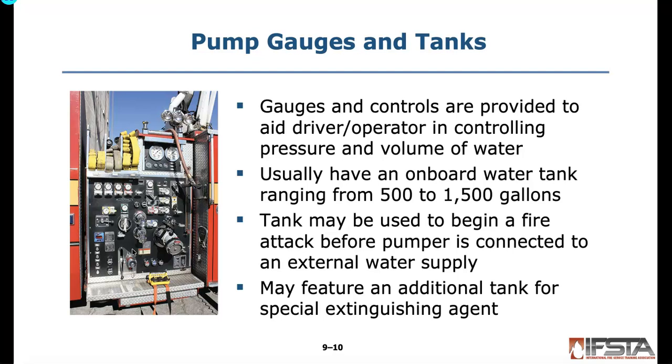So you don't want to, if you draw too much water out of your tank, you'll end up cavitating the pump, right? So you have to make sure you have a water supply established at some point before you use up all the water in your tank.